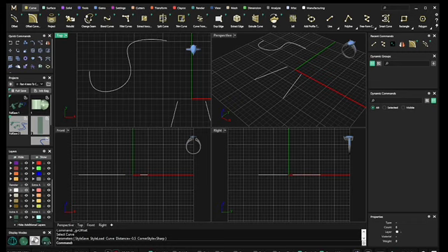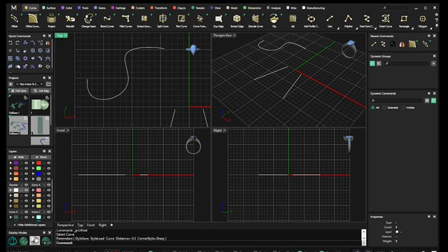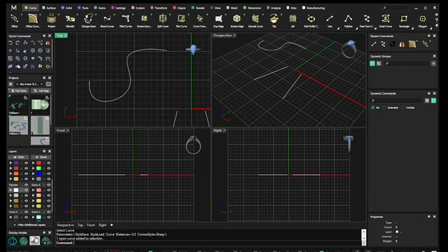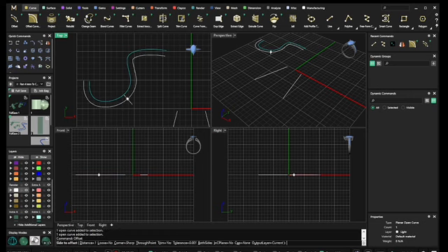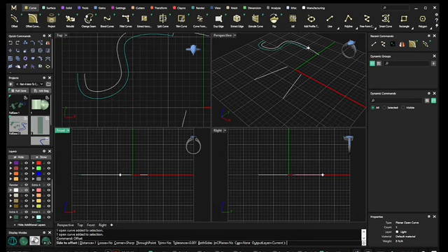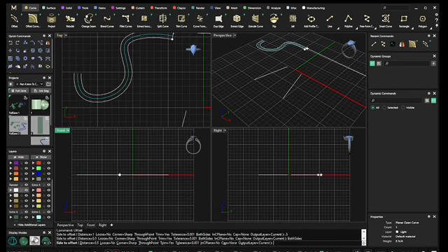We've talked about this briefly, but Matrix is a plugin to Rhino, and Rhino has some basic commands. So one of the basic commands in Rhino is offset. I'm going to turn the gumball off because it's a very distracting tool. If I select this and type in offset, press enter, I can type in the amount. Right now it's at 1. I'll type in 0.5, and I can click and do one side, or I can do both sides.